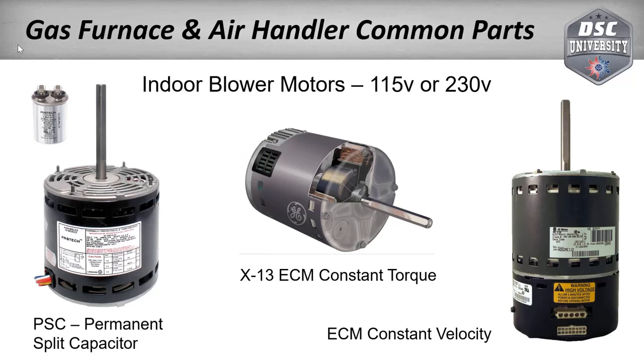So any furnaces that we still had in stock that had the PSC motor in them, we could continue to sell them. The manufacturers just couldn't build them anymore after July 1st of last year. With the X13 constant torque motor, a lot of people get confused about that motor. It's an electronic motor, and the reason it was named the X13 motor is they developed this motor back in 2006 when the industry went to 13 SEER minimum.